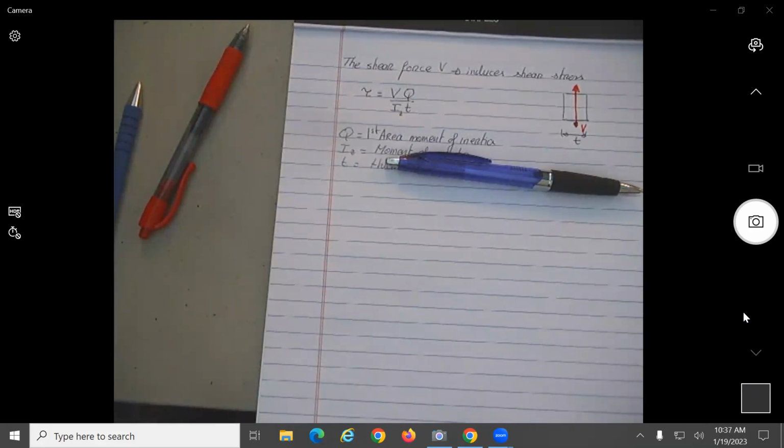No, that twist now is shear. So what is the assumption that generally you have been making is that the structure is thin and long, or a slender member, no? So all the equations you have derived so far for stresses and bending, you have been making the assumption of long, slender structural members, okay? Or they are much longer than the width.